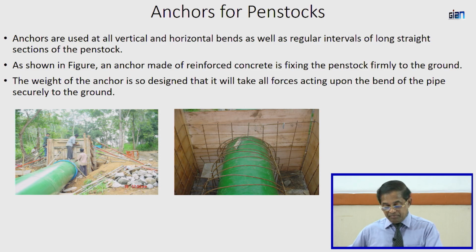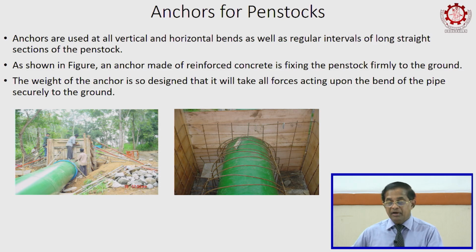Here is an anchor, right. Anchors are required, we will look at the forces later on. Anchors are required to hold the bends, pin the bends down to the earth, so that unnecessary forces cannot move the penstock, right. In an anchor you do not need much strength, you do not need a lot of reinforcement. What is needed is the weight, right, what is needed is the weight.